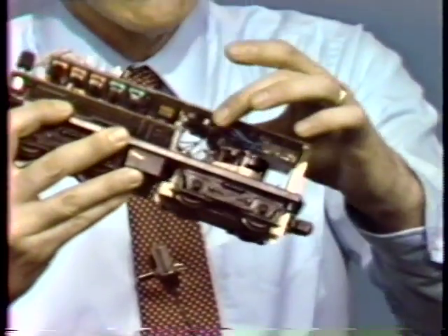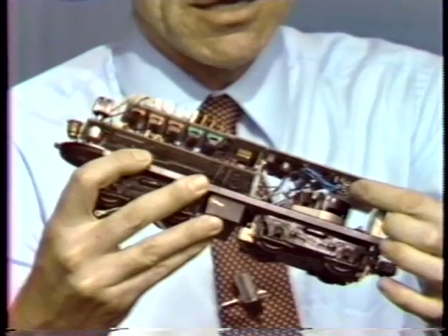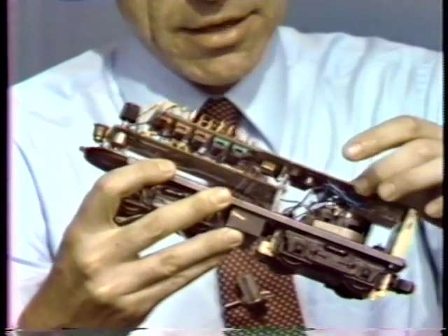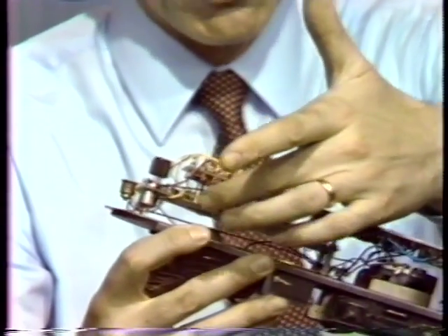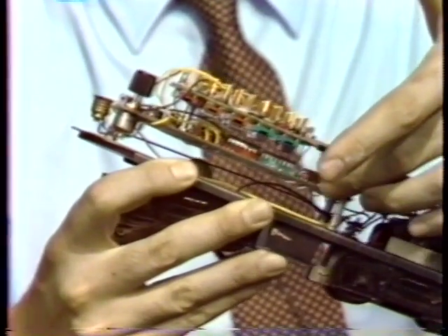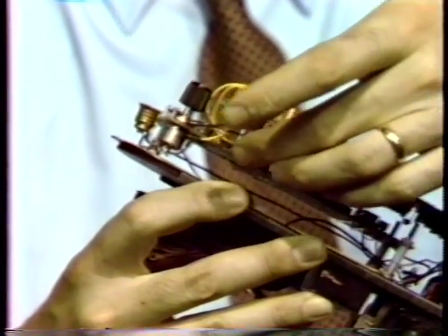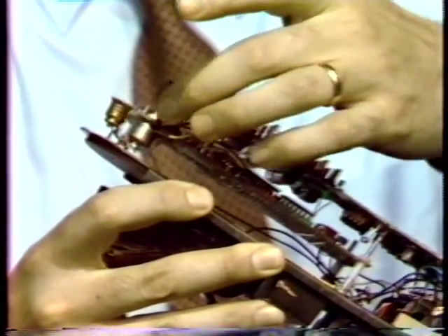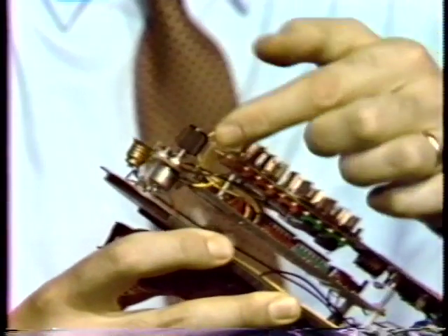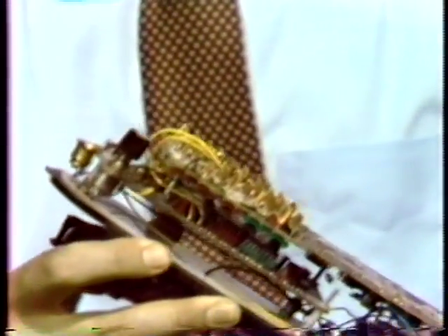And the power amplifier is back in this rear section, a reversing relay in here, which I haven't exercised, but there is a reversing relay, and the power amplifier itself, and as I say, I'll talk a little bit about how that works later. The bottom board is simply the circuit that gives me the command pulses. In the usual normal system, this would be replaced by the board that receives commands via the time division multiplex telemetry system. So for our purposes, we have a board here that provides speed pulses. The frequency of those pulses is controlled by the potentiometer on the board, but that's simply for demonstration purposes.